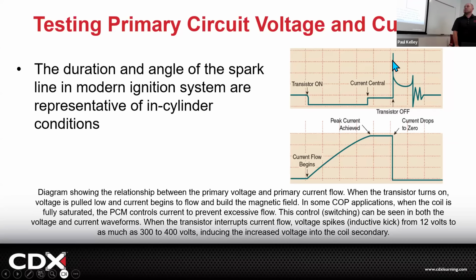The height of this line is going to be very critical, right? And then the spark is going to continue for an amount of time, and the shape of this line is very critical. Then the spark is completed, and this is it discharging, oscillating like it's using its last little voltage. Then we have to turn the transistor back on to charge it.